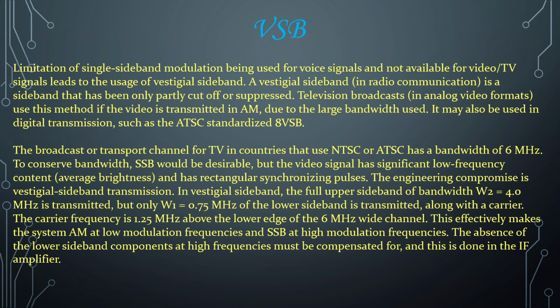To conserve bandwidth, SSB would be desirable, but a video signal has significant low frequency content, average brightness, and has regular synchronizing pulses. The engineering compromise is vestigial sideband transmission.